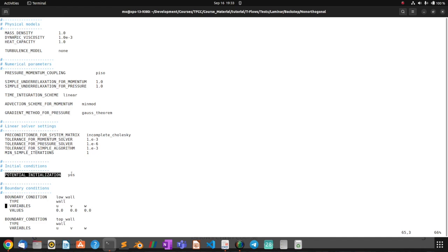And here we come to an interesting part, because in initial boundary conditions, you need to initialize. The initial conditions for each solution, you have to start from somewhere. And if you initialize the domain by an arbitrary value that is very far from the final solution, then you take longer to iterate in order to arrive at the correct solution. But if you start from a somewhat closer solution to the final one, then you are more likely to finish the convergence in a smaller time interval, obviously.